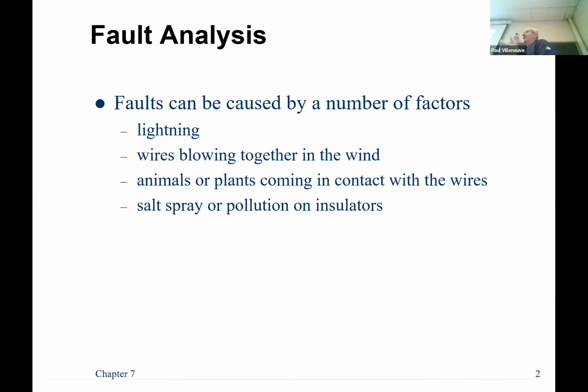So if they see a wire that has insulation, if it's got a type of insulation that they find tasty, I guess, they'll start chewing the insulation, and then they can cause an arc there. And those tend to be much worse because that's a big arc, and that can cause a lot of problems. Plus, the cable is insulated, which usually means that it's not designed to be close to grounded structures. So if you chewed away the insulation, you can cause a lot of problems.